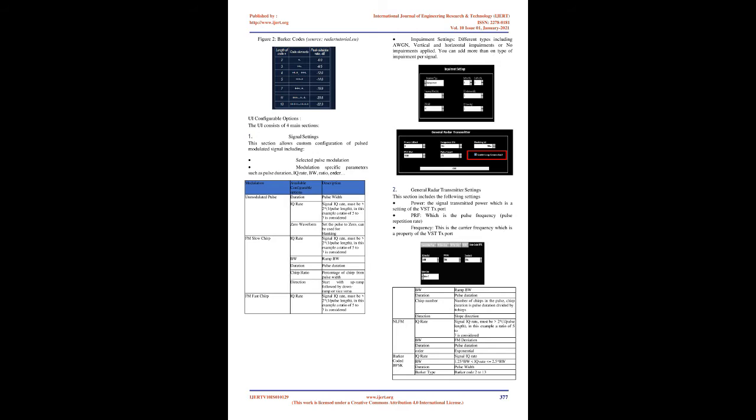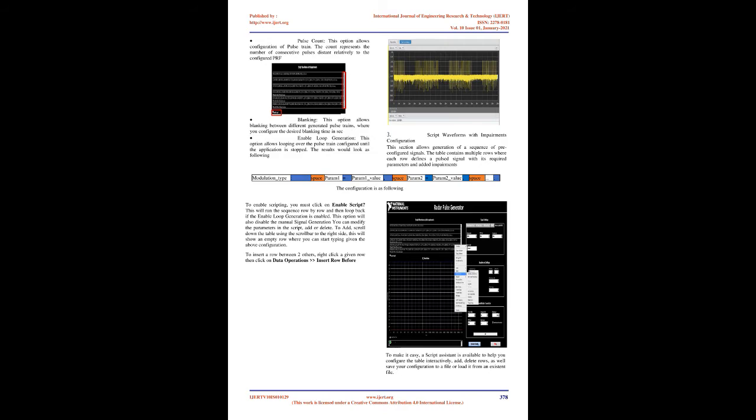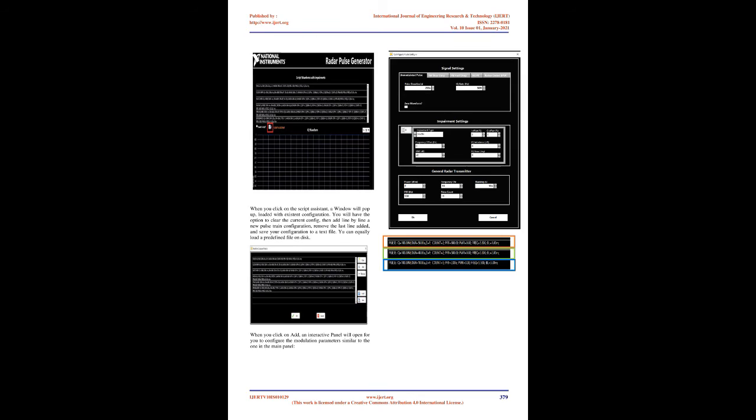1. Unmodulated pulse, a standard pulse with configurable duty cycle, duration, and IQ rate. 2. FM slow chirp, a LFM modulated signal with an up ramp and down ramp and configurable chirp length or ratio of the entire pulse duration. 3. FM fast chirp, a LFM modulated signal with a configurable number of up chirps where the pulse duration is spread evenly over the configured number of chirps. 4. Nonlinear FM, NLFM, a nonlinear FM compressed pulse with configurable exponential order.